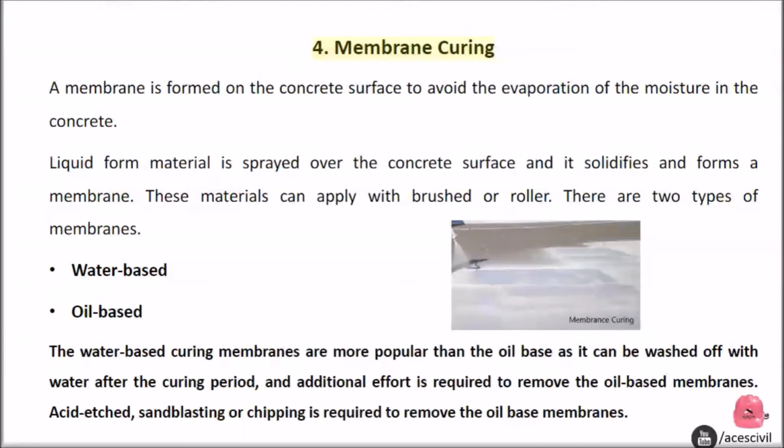4. Membrane curing. A membrane is formed on the concrete surface to avoid the evaporation of the moisture in the concrete. Liquid form material is sprayed over the concrete surface and it solidifies and forms a membrane. These materials can be applied with a brush or roller.